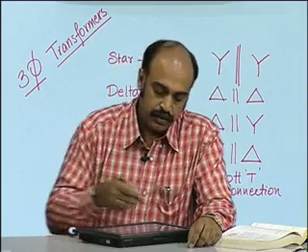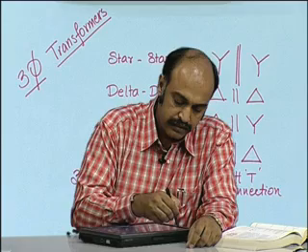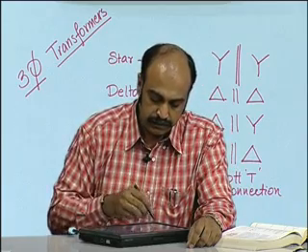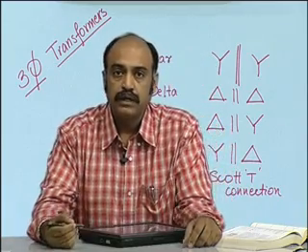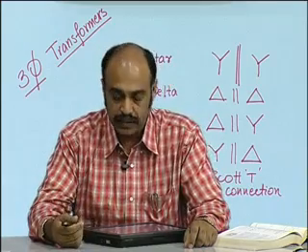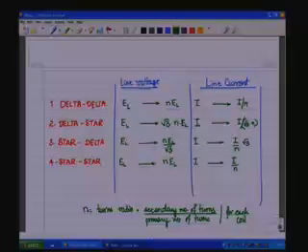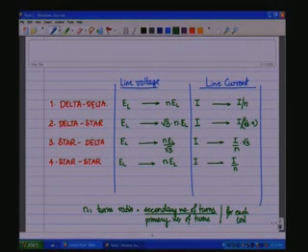And then we summarized towards the end of the last session the 4 different types of 3-phase transformers, as I am showing it here on the page. The relationship between the line voltage and the line currents. You see that in the delta connection, the terminal voltage on the secondary side is just a factor of n times the primary terminal voltage.